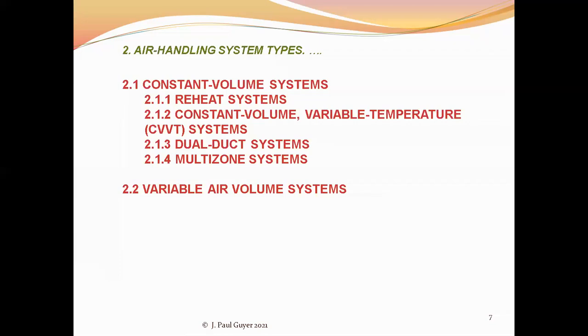And there are two things that the thermostat can do in one of these zones. You can have a system where you just have a little damper back where the 10 zone ducts take off from the fan, and these dampers open and close in response to whatever the thermostat in their space is telling them to do.